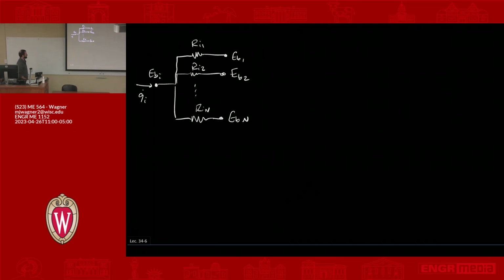The challenge is that you're going to have an unknown emissive power, potentially, because you maybe don't know the surface temperature. You have unknown heat flow. We're going to need to use the geometry of the problem to calculate the resistances. But we're going to end up with, this is for node I, so this gives us n unknowns,